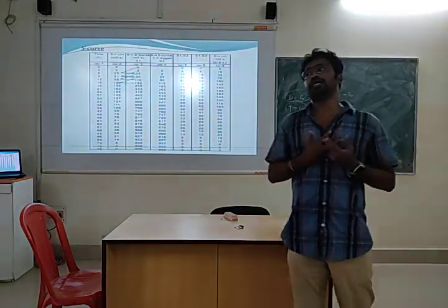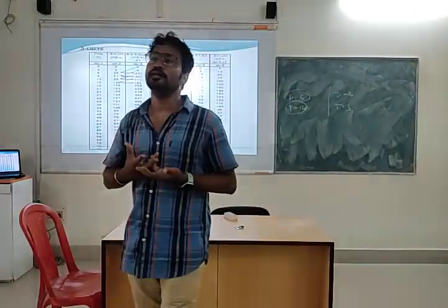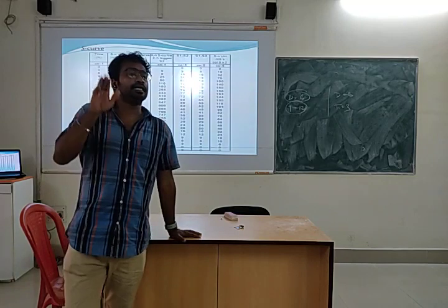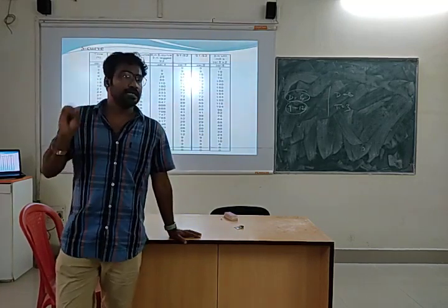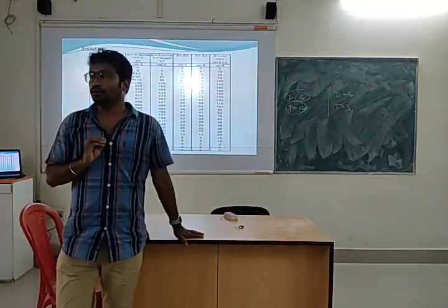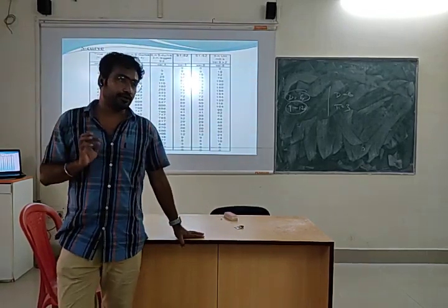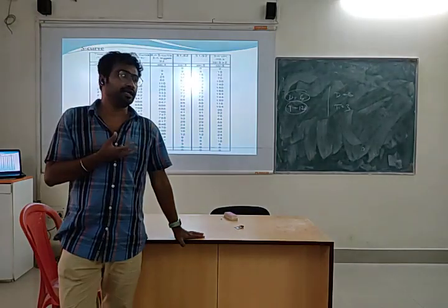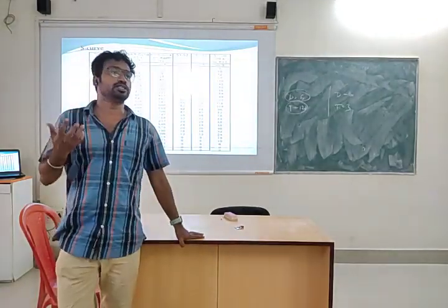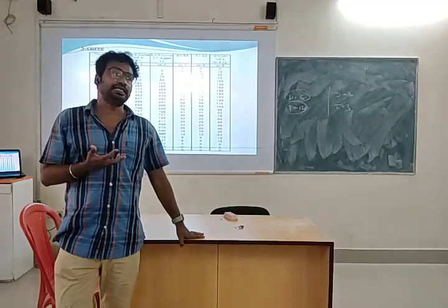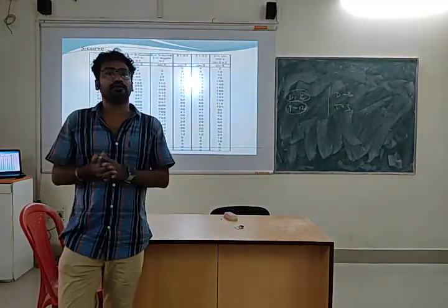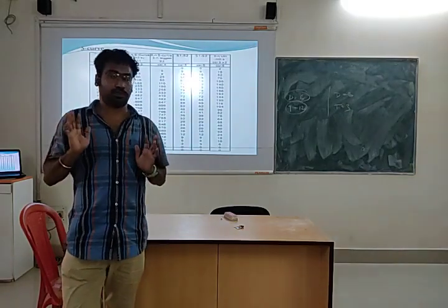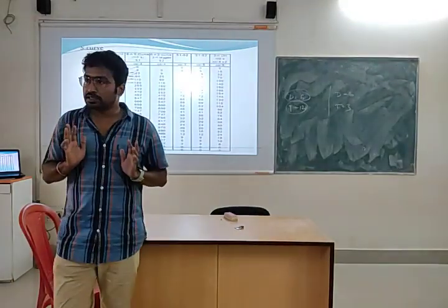That is, you can say a fixed hydrograph for a catchment area, right? And we multiply the excess precipitation, excess rainfall, with those ordinates, and we get the flood hydrograph. Okay? And in doing so, some constraints were there. That is, the duration will be fixed. That is, a D-hour unit hydrograph can be used only for a D-hour duration of precipitation.